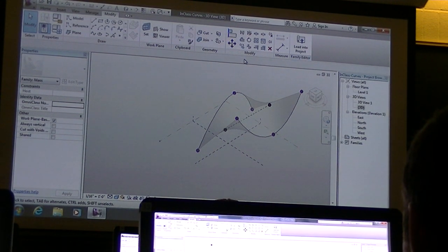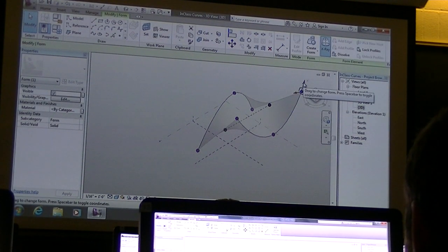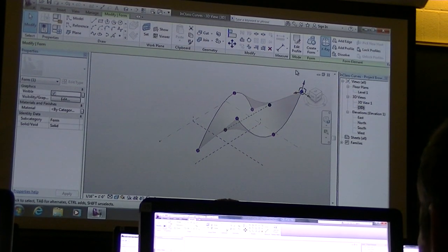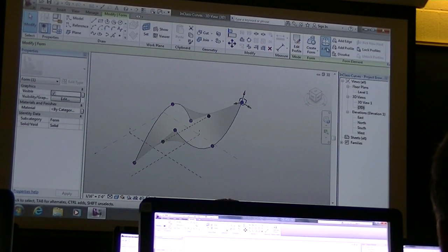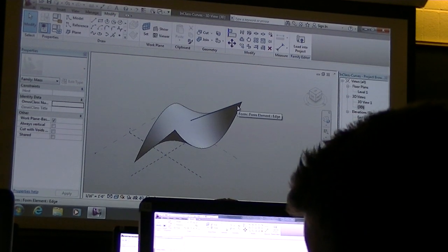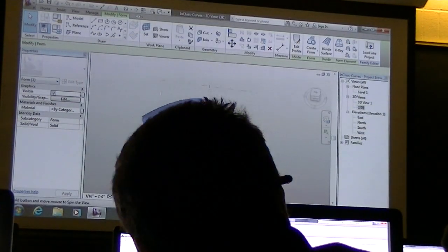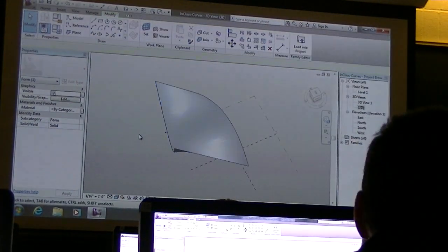Sometimes these 3D views get kind of corrupt from time to time, and when I say corrupt, all of a sudden the ability to select your points and move them goes away. And what you guys are saying is if you toggle the X-ray back and forth, it should bring it back. It's kind of refreshing the screen. It's not really that clunky, but all right.